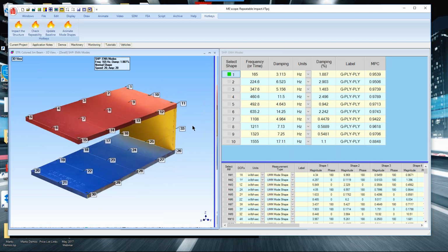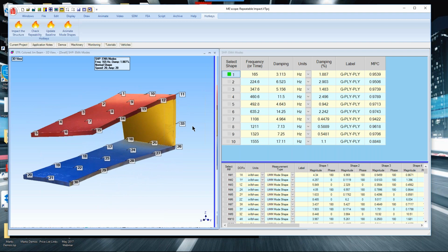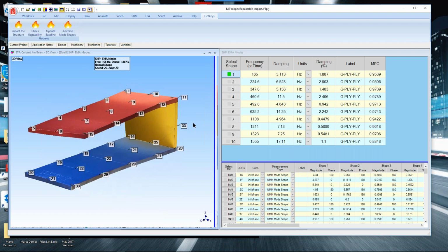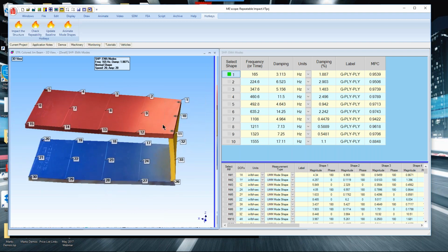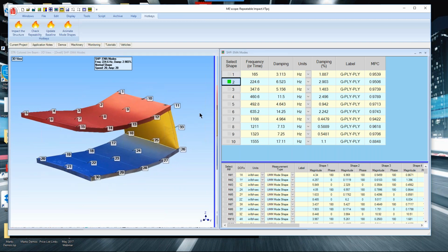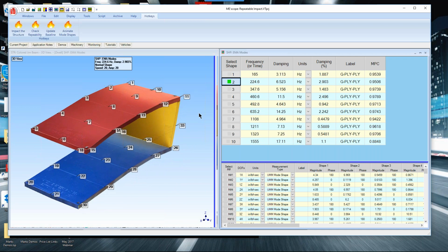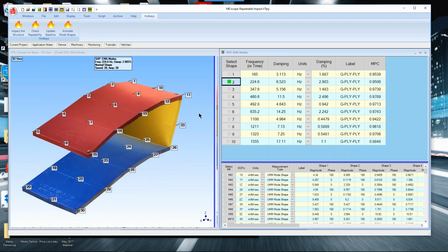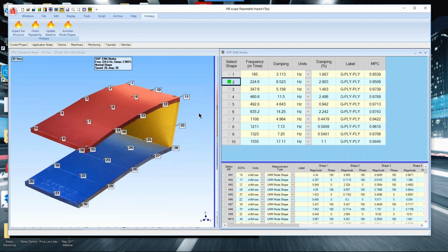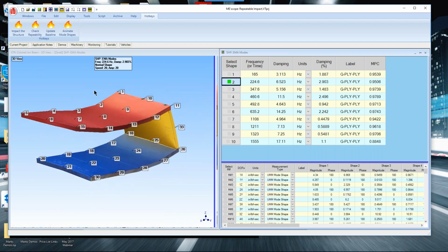If you take a set of data, I don't care what it is, an airplane wing, a car body, a machine tool, and you don't see something that you can identify as first torsion or first bending, here's some simple bending of the top and bottom, then you probably don't have a good data set. You should see those modes in virtually anything that you analyze.